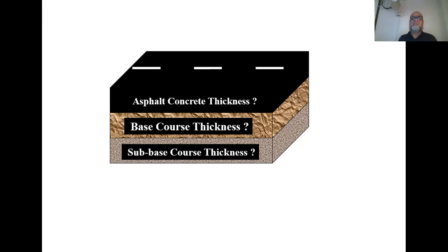Obviously, when you say base course and subbase course, they are sometimes used as synonyms, because base and subbase are both aggregate bases, but the subbase uses larger size aggregate, and its value is lesser, because the concept is to provide the best material at the top of the layer, because the stress is maximum at that point where the tire is in contact. As you gradually go down, you can have lesser material, because the load demand at that point is decreased.